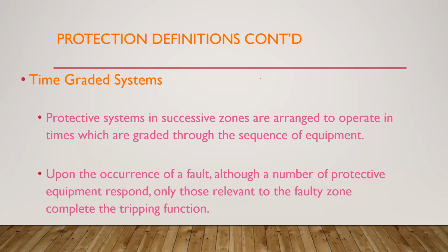All right, sir. One question, sir. In terms of protection, in an incident like that, why wouldn't they open and shed the load to keep those generators? But we don't protect load. We don't protect load. We protect the system. The load is protected by the owner of the load.